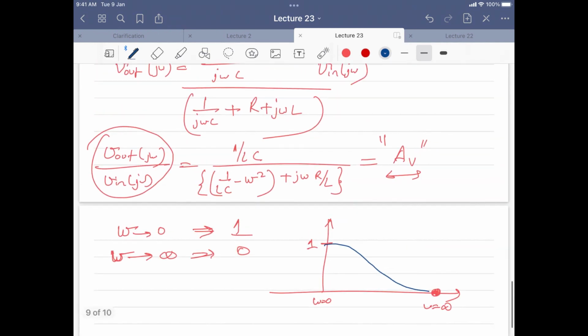because it is passing certain frequencies. Let us say omega c dash here, it is passing certain frequencies with a gain of, let us say, 1 or close to 1, that is close to 0.887. So we are not going into the details of it, but just to tell you that in this region the gain is high, and after that the gain reduces drastically, and these frequencies will be reduced to a small value, though you will not get exactly 0 because it's a practical circuit.